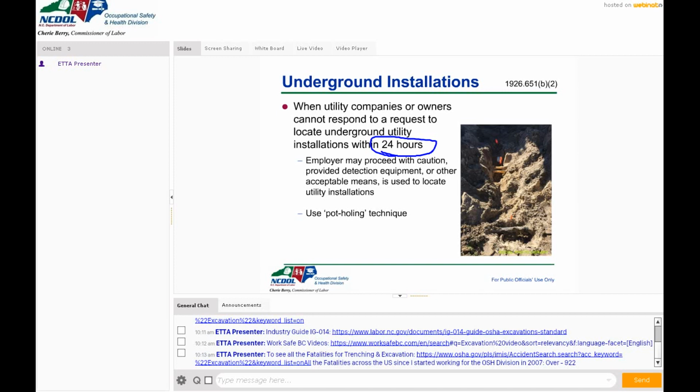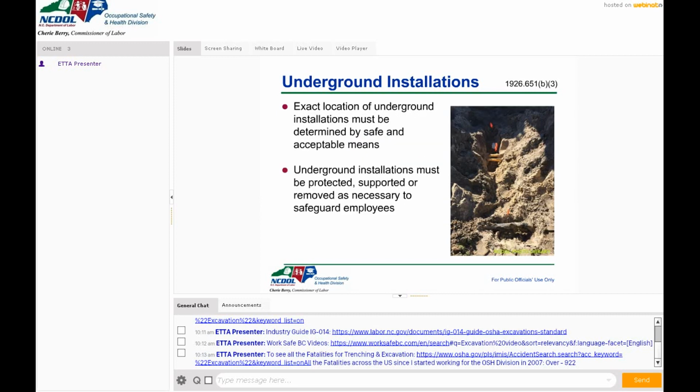Now, keep in mind that if you are digging up next to a utility, regardless of what it is, you're going to have to support it as well once you dig the material out from around there. And you want to dig it very safely. A lot of people are not aware, but when you go to their website, they actually have a little manual you can download. And the manual talks about how you dig up to the underground utility as well. Because you certainly don't want to be using a pick and there's a high voltage power line buried there, or a gas line buried there.